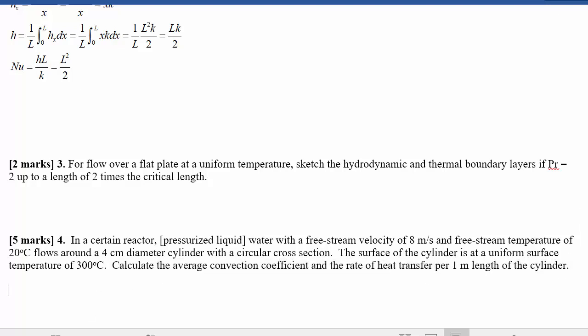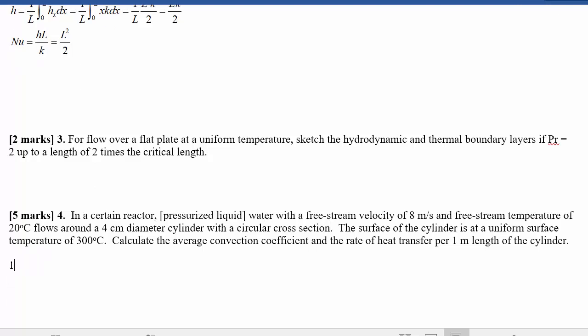So to do this, we're going to be figuring out the Reynolds number. Find the Reynolds number. Then we're going to find the Nusselt number. Maybe we'll also figure out some parameters. So maybe the 0th step would be get parameters, which we're probably going to need what?